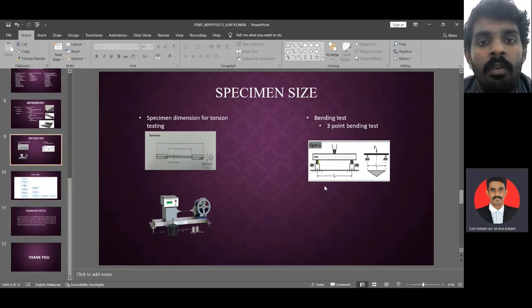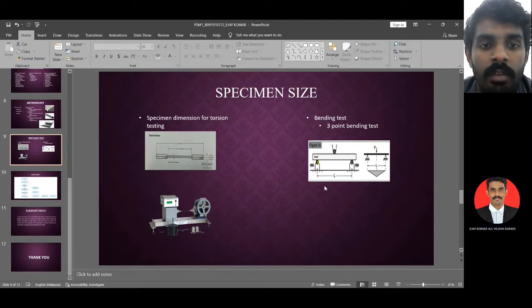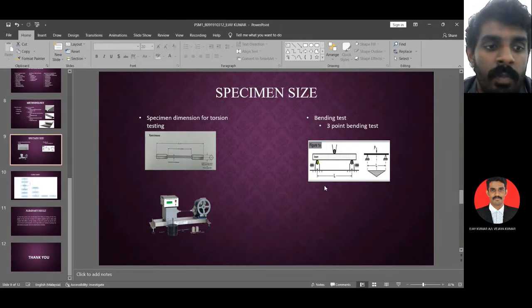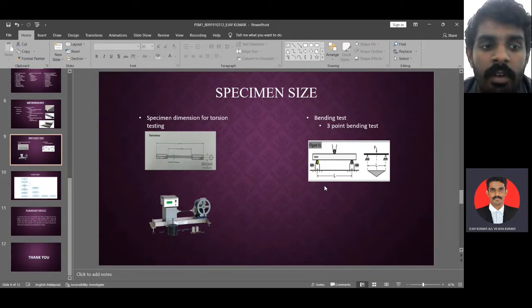And now for the procedure of experiment. First of all, for torsion testing. For the torsion test, before starting the lab, calculate the maximum load that can be applied to the rod, assuming a limit of 75 megapascal, and measure the diameter and length of the rod, radius of the pulley, mass, and any other relevant data. Then we set the angle.